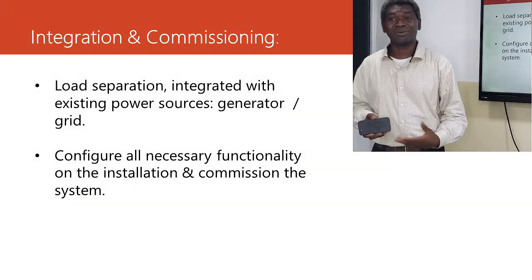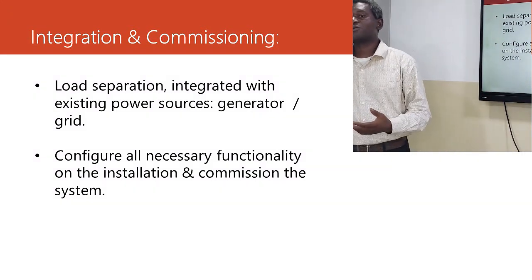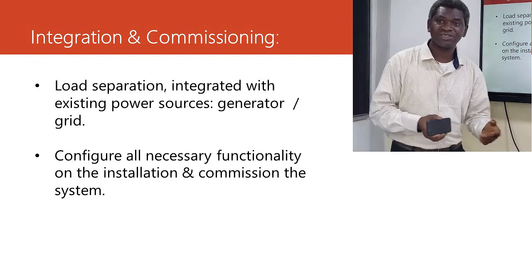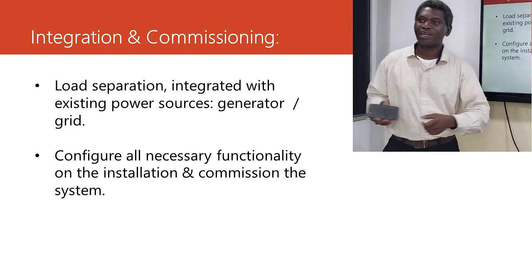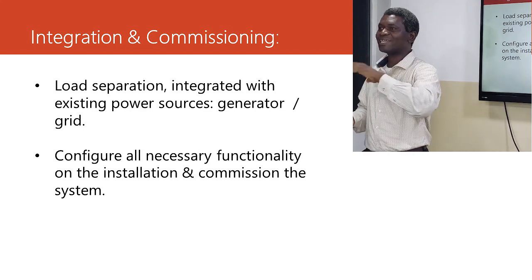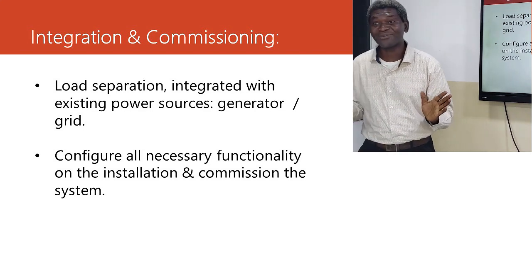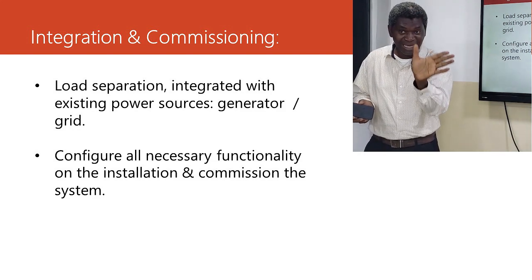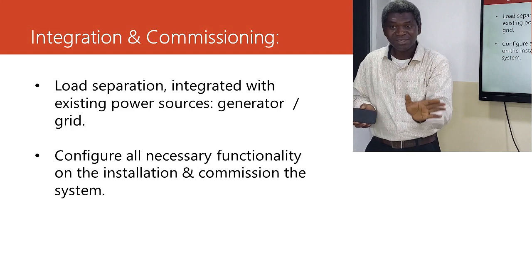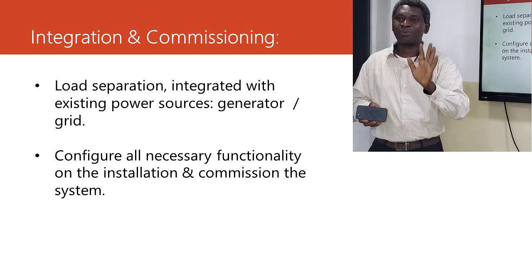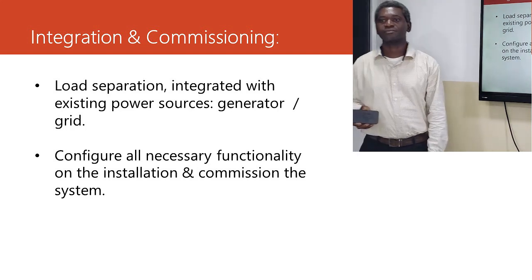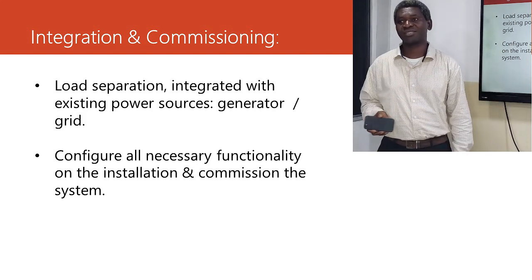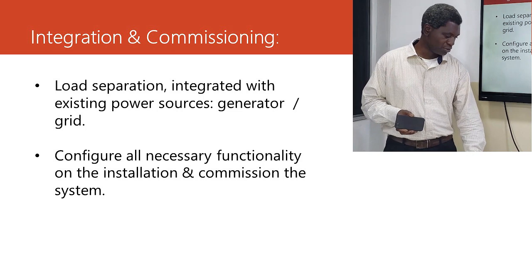All these steps are very important. So we should avoid saying, okay, you have installed the inverter, you've connected the battery, you've done all your connections, and you switch it on back. Oh, there's light now, everything is working. No, you have not finished. Go to the inverter, check all the functionality, configuration, defaults. Make sure they are set properly and you save it. Then you are finished, and that means you have commissioned that system. That's how it should be done.